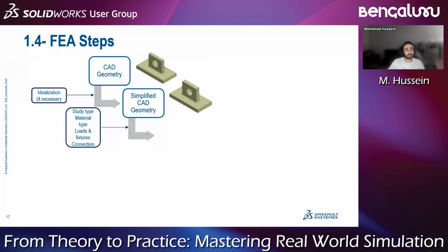If you are working with an assembly, you need to define one extra thing. What is this extra? It is about how parts are connected together. Because if I have an assembly, some parts may have the degree of freedom to move, so I have to define how these parts are going to interact together. But in case you are working with a simple part like the one I'm showing right now, you don't need to define any kind of connection.